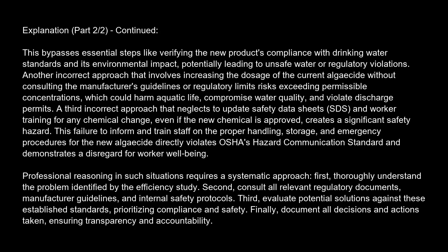This bypasses essential steps like verifying the new product's compliance with drinking water standards and its environmental impact, potentially leading to unsafe water or regulatory violations. Another incorrect approach that involves increasing the dosage of the current algicide without consulting the manufacturer's guidelines or regulatory limits risks exceeding permissible concentrations, which could harm aquatic life, compromise water quality, and violate discharge permits.